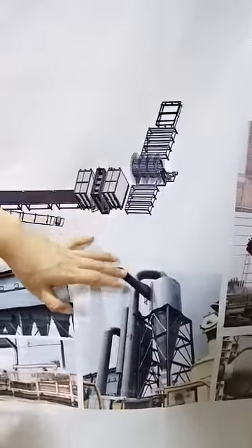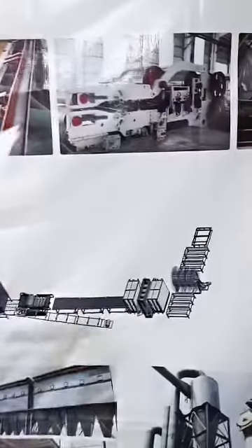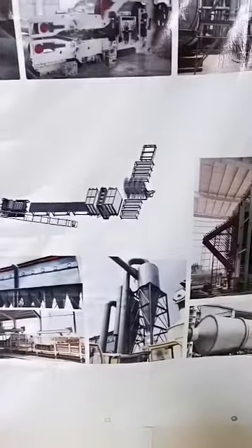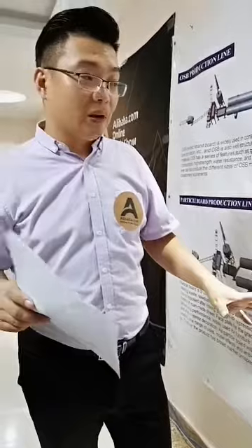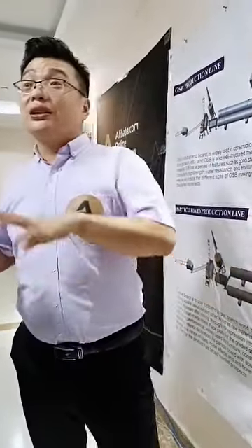Here, the hot press, I can say, is the heart of the particleboard production line. Actually, the number of layers of the hot press sometimes decides the capacity of the whole line. For the particleboard production line, the first thing is to make sure of the capacity. Making sure the capacity means we need to calculate the layers of the hot press.